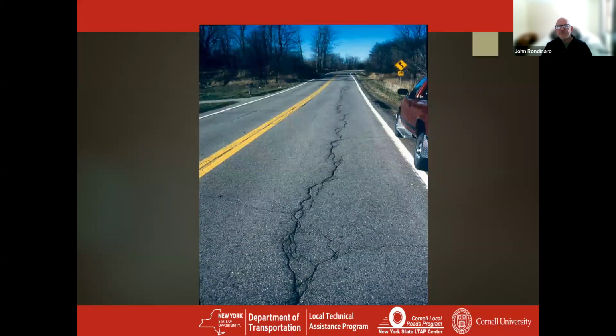And here's a case. Quick, raise your hand, who thinks this is a good candidate for crack sealing? Jody, what do we got? Nothing yet. Well, I'm going to take that as an indication that people are saying this is not a good candidate. And actually, they are correct. David, you're right. That is not a good candidate because it's got a ton of interconnected secondary cracking.